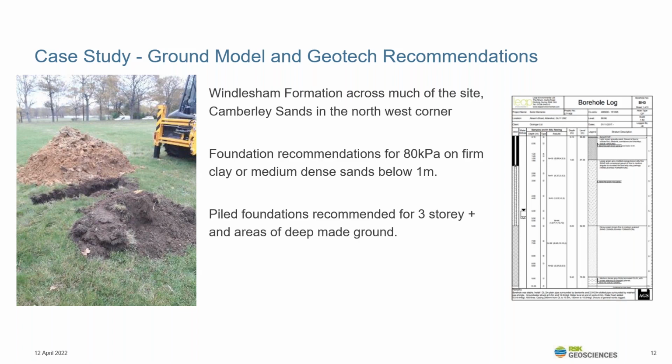Camberley sands outcrop in the northern corner of the site, which comprise medium dense to dense sands. So our foundation recommendations are a bearing capacity of 80 kPa, founding on the firm clays or medium dense sands below a metre. Piled foundations were recommended where there were 3+ storey apartment buildings or where there were any areas of deep made ground on the site.